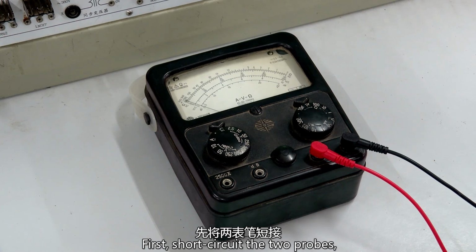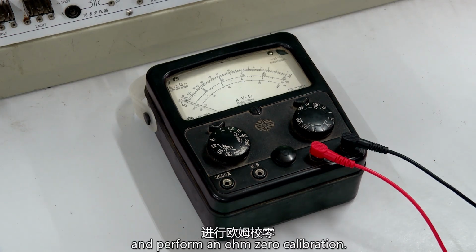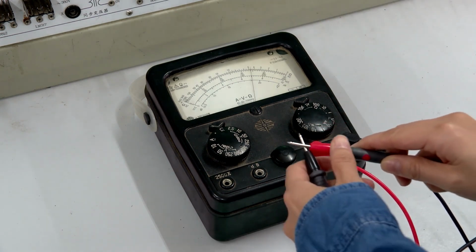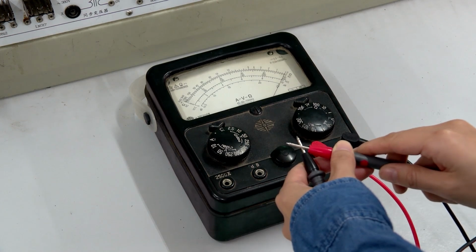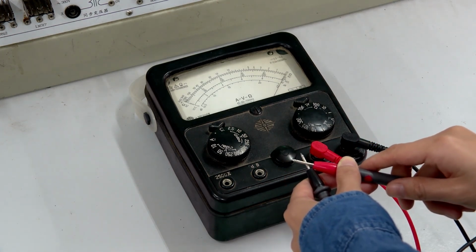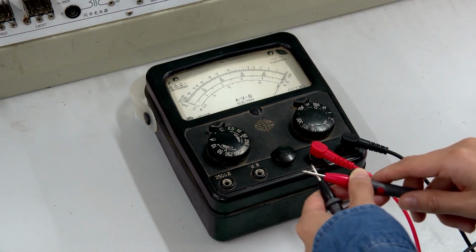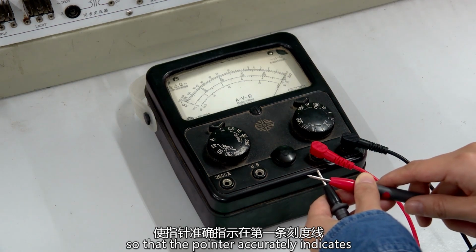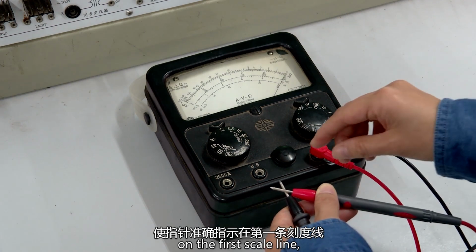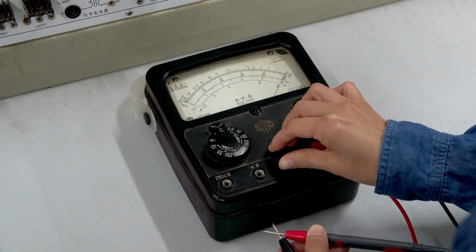First, short-circuit the two probes and perform an ohm zero calibration. Adjust the ohm zero knob so that the pointer accurately indicates on the first scale line, where the right value is 0.